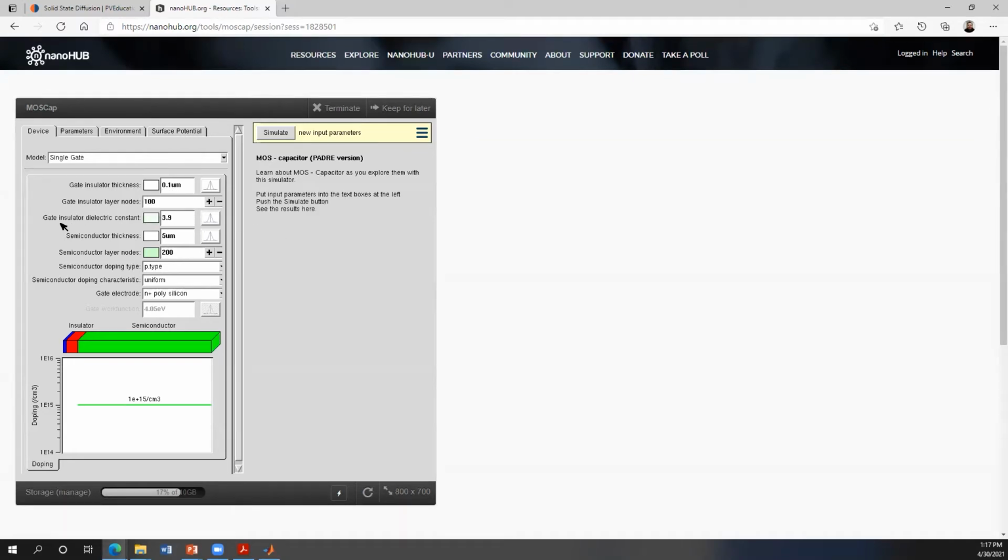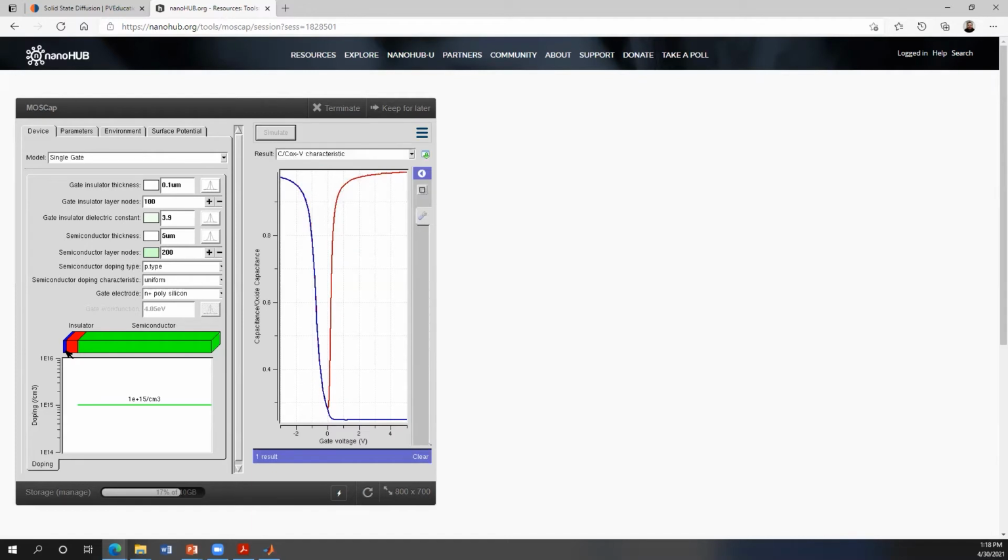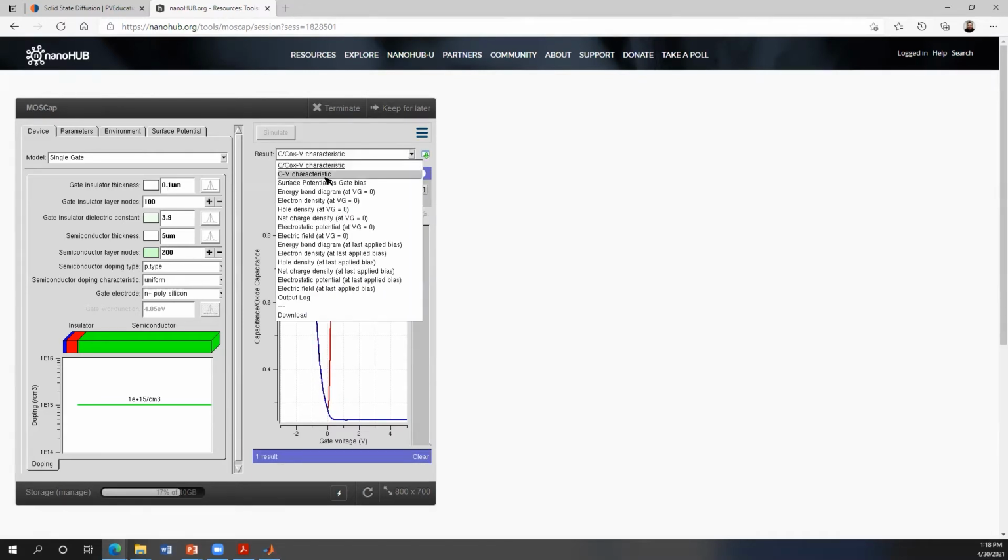And then we know the dielectric constant here. Think about it like refractive index, dielectric constant. It's given as 3.9, okay? Let's run this case. You can just put your electrodes and try to measure the capacitance that you get out of it, okay?